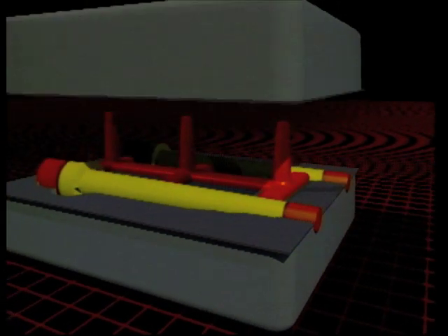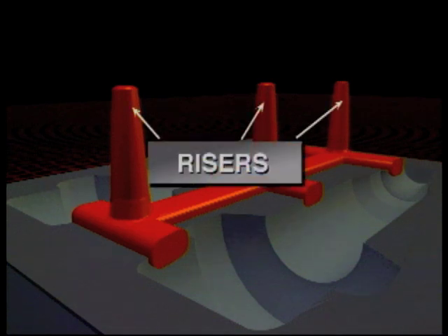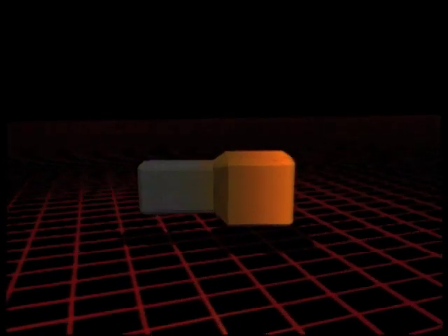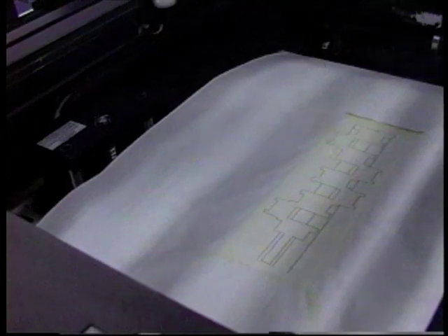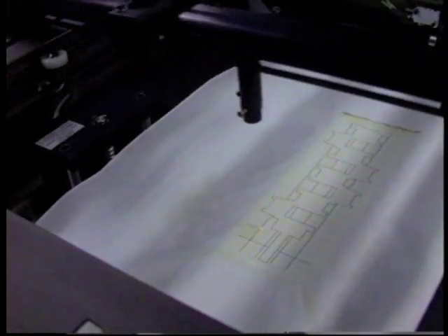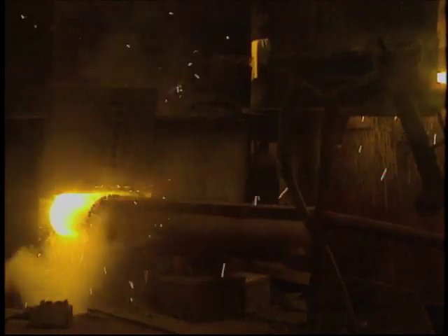The location of the casting placed in the mold and the placement of risers, chill, and gates is important. Vertical surfaces in the mold need draft. Fillets help to eliminate stress points and improve casting integrity by eliminating hot spots. These are typical of some of the numerous details to be worked out by the design team. The design engineer, along with foundries, use advanced technologies such as rapid prototyping and computer-aided design tools. Special molding processes like investment casting and centrifugal casting offer unique value to designers.